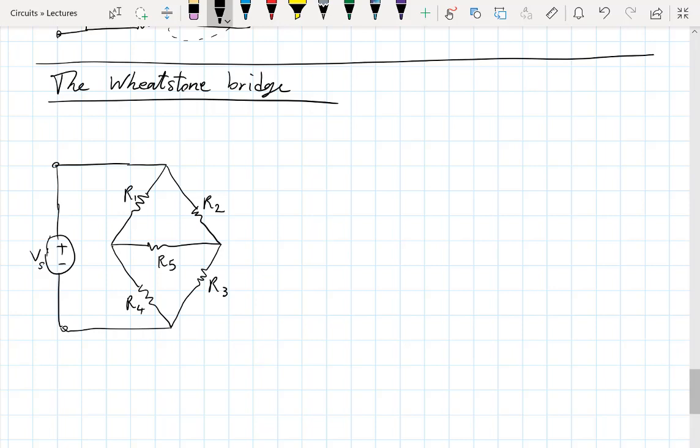Well, if I ask you to solve this circuit, first of all, let's say you don't remember anything about equivalent resistance and linearity and superposition and Thevenin and Norton and all these things, wye-delta transform. Ultimately, doesn't matter as far as the circuit solution is concerned. Write your KVLs, KCLs, element relationships, solve the equations, you will get your answer, right?